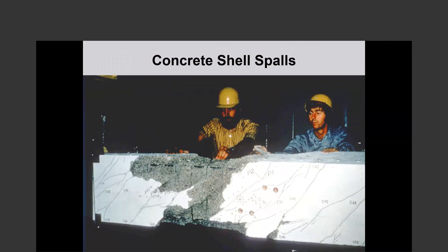Now, if you keep on increasing the torque, initially the corners of the cover will begin to spall. The concrete is under compression. If the compression becomes high enough, the concrete will begin to spall, typically at the corners, and then it will spread, and ultimately we will lose much of the cover. So in torsional design, we depend basically only on the steel cage.